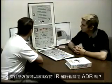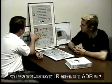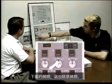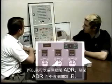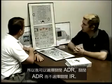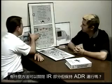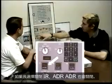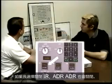Is there a way that I can leave the IR running but turn off the ADR? Sure, the switch down below here, these are switches, so I can select the ADR off without selecting the IR off. Is there a way that I can turn off the IR portion but leave the ADR running? No, if I select the IR off, the ADR is coming off as well.